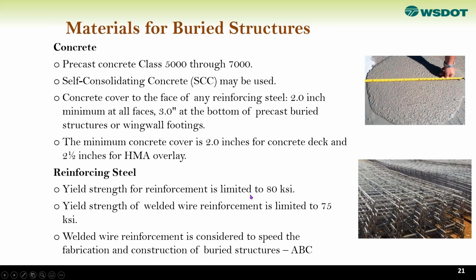The reinforcing steel we are using is up to 80 KSI, and we are also using welded wire fabric. This is another way of accelerating bridge construction. The design limit that we have for reinforcing is 75 KSI.